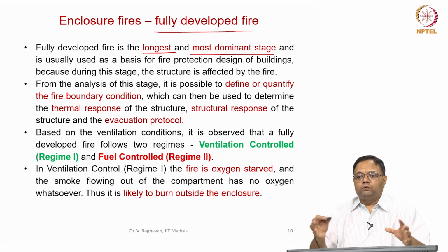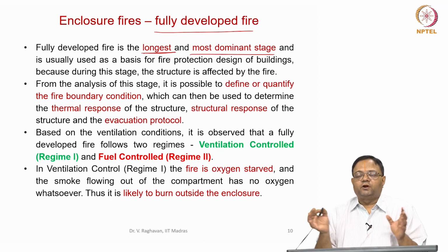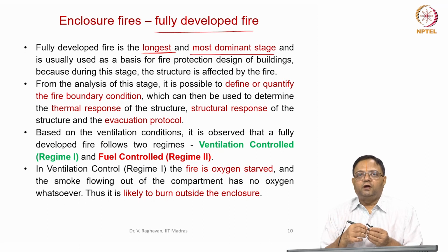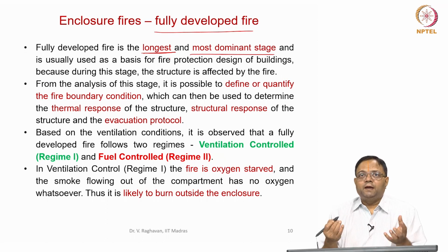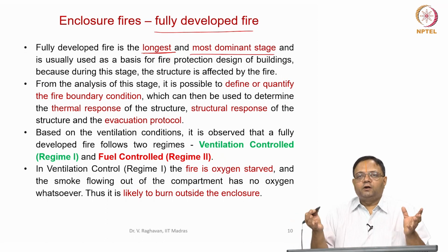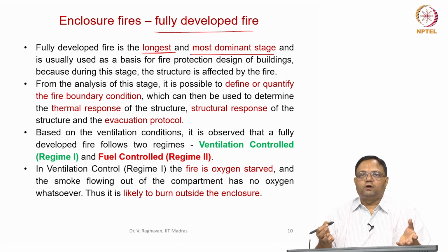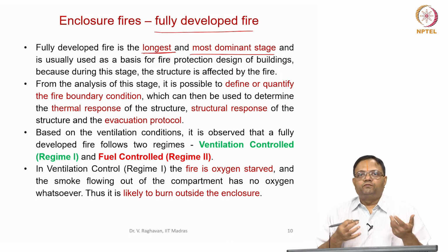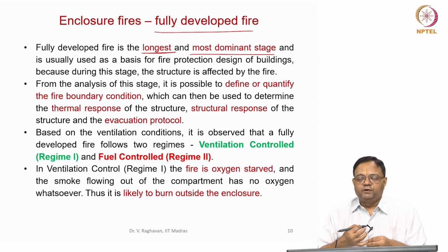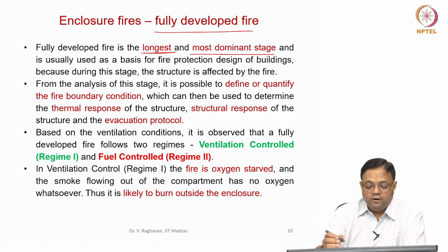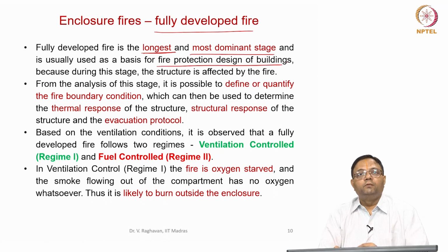That is, if you have a compartment with several commodities, you know what is the fuel load in that. Based upon the fuel load, you will know the time required for burning all the commodities. You know the flammable characteristics of these materials. Then using this as the basis, we can design the fire protection of the buildings.